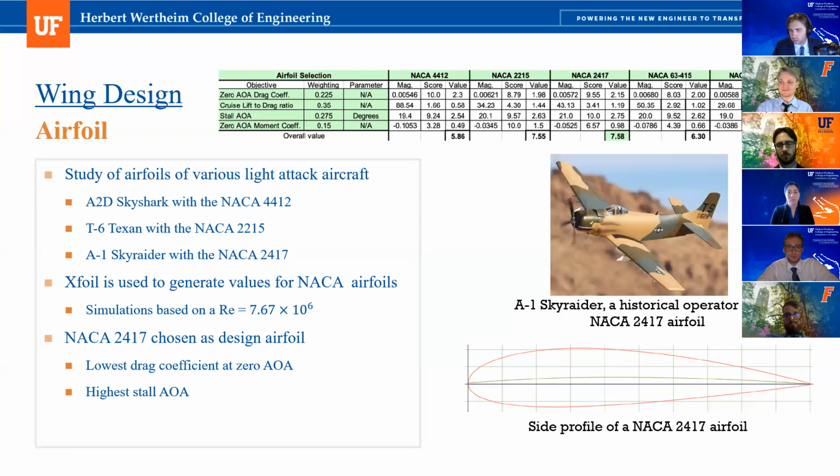So to show all the parameters, and then we can use that, okay, there's a thrust weight ratio requirement, and we have the initial weight estimation. So we know that when we do the power plant design, we know what is the target thrust we need to generate. And for the wing design, what is the lift our design wing should generate, or lift drag ratio, right? Or wing loading. So that is in detail.